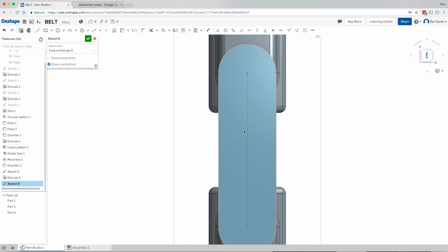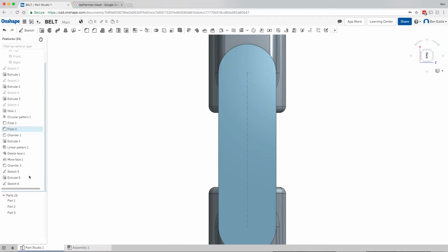If you're going to drill holes and you're going to use the hole feature, the points that you use need to be on the face of what you're going to drill through. So this is why I'm creating another sketch here. And I'm going to make that sketch so that that point is concentric to that circle, and that point is concentric to that circle, and that's all we need for this whole feature. At this point, I can hide this sketch.